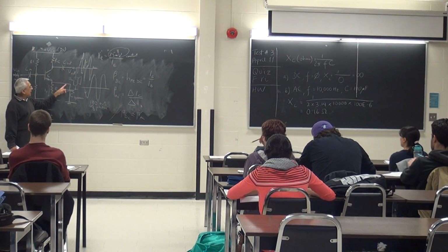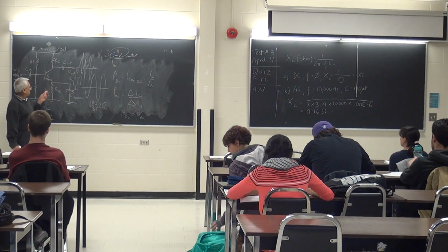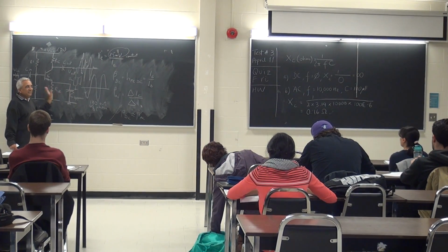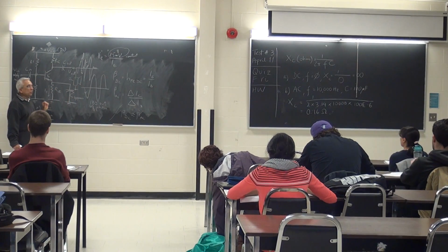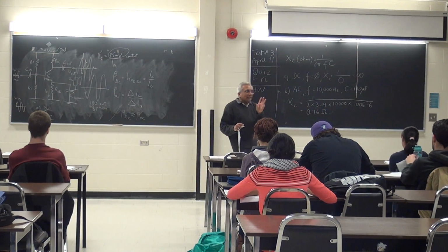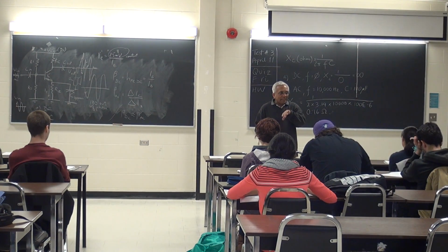Is my signal now tied to ground here? Right? 0 ohms here, 100 ohms here. This is not going to be seen, right? This is shorted. Basically, this point emitter is shorted to ground. So that's what's happening. That's why we call it a bypass capacitor. We're bypassing RE. Okay? Good.